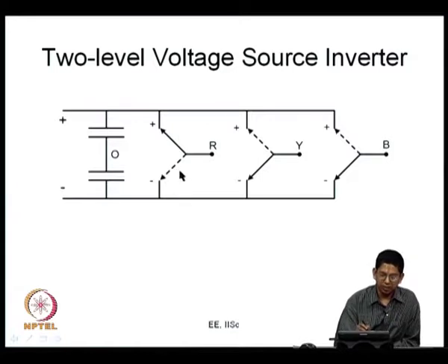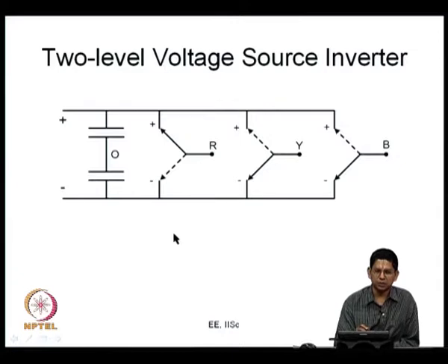In case of IGBT inverters, many times they switch on the order of kilohertz. Typically, IGBTs switch up to 20 kilohertz, so you may find about 5, 10 or 20 kilohertz. These all depend on the choice of device, the application, the rating, etc. As you come to still higher power converters, you switch the devices at lower frequencies. As the rating goes on increasing, the switching frequency is low, and at very high power levels you tend to switch at fairly low frequencies.